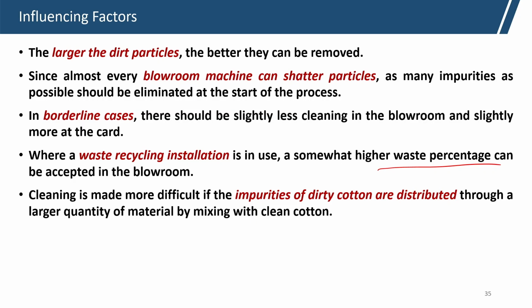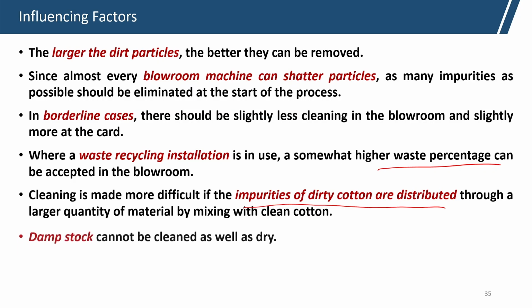Cleaning is made more difficult if the impurities in the dirt particles are distributed throughout a large quantity. So, it is basically distributed and mixed in a large quantity of clean cotton. Damp stock, that means higher moisture, as I have mentioned, cannot be cleaned as well as dry particles. So, if it is moist cotton, it cannot be cleaned easily.